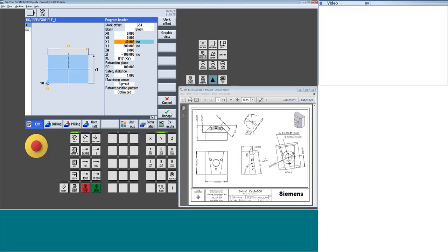I'm going to set my values to absolute. And we're going to say we got overall width is 100 millimeters by 100 millimeters. I don't have any positive stock because we're going to machine a 9-degree plane, so I'm not too worried about it. My thickness is off my print, 65 millimeters, so I want my top of my part to be 0 in this case. So I'm going to say that my stock exists in the negative direction.